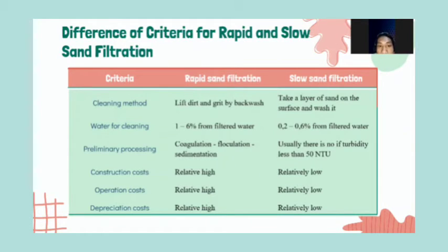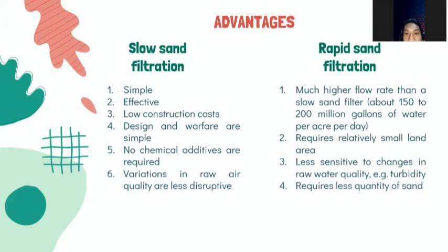Next, the criteria are cleaning method, water for cleaning, preliminary processing, construction cost, operation cost, and depreciation cost. As we can see, the rapid sand filtration has a relatively higher cost than slow sand filtration.